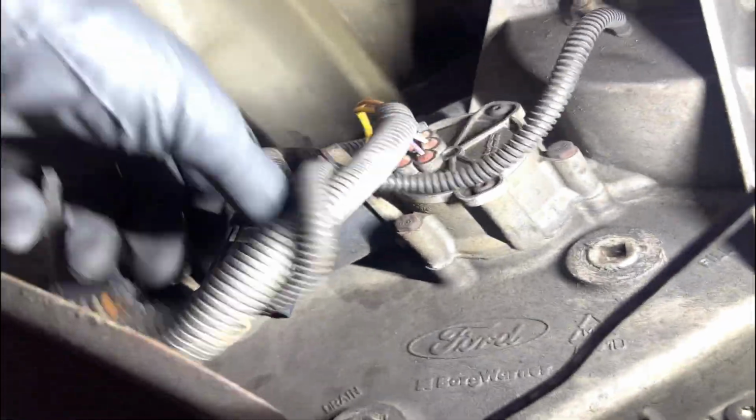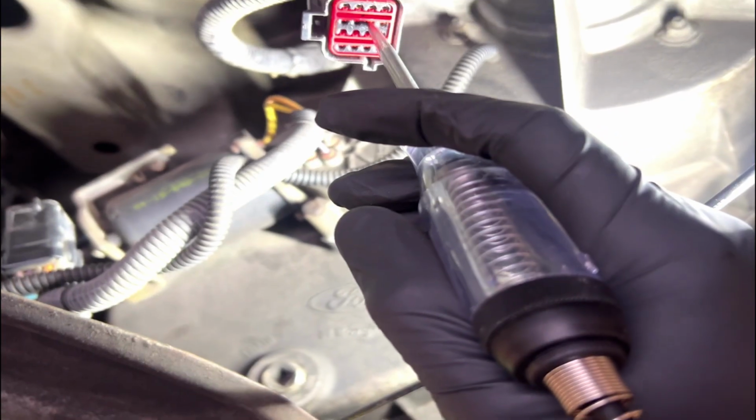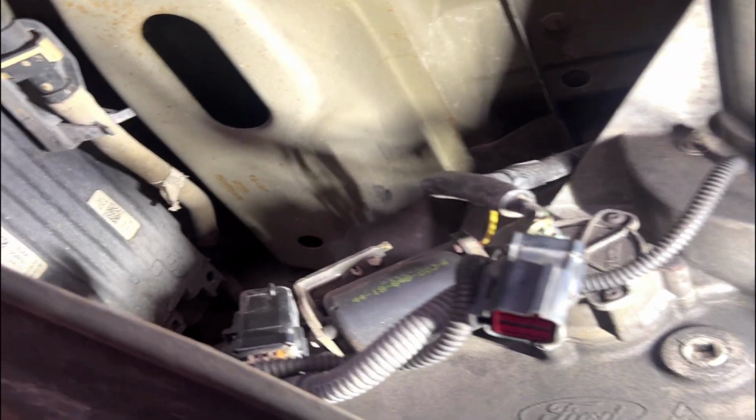So we got a 1/4 amp test light. Now hooked to positive. So this is looking for ground. So it finds ground to a light. We don't know. There should be ground, but I mean it should be pretty low current. Might have to get an LED test light. And so our pin is this one right there. We have no light.